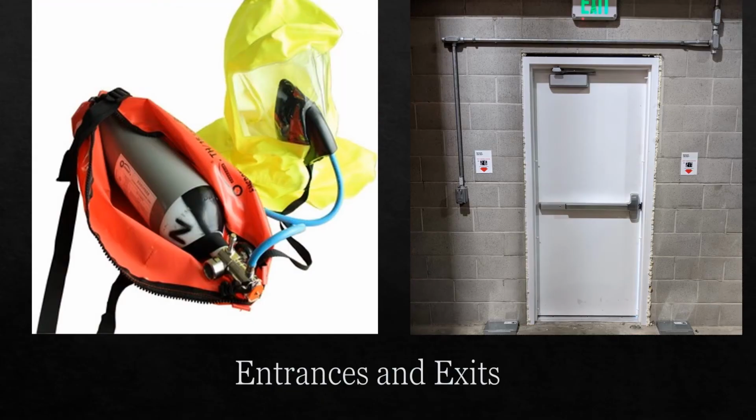Section 7.3.9 requires that machinery rooms exceeding 1,000 feet squared have at least 2 exit doors. Appendix A provides explanation that where installing a second door is impractical, the owner or operator should provide an alternative escape method, such as the use of escape equipment. Machinery room doors must be self-closing, tight-fitting, equipped with panic hardware, and swing in the direction of egress.